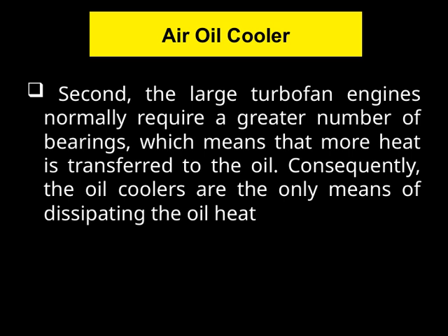This is where oil coolers come into play. They are essentially the only means we have to dissipate the heat from the oil. Without effective cooling, the oil could overheat, which could lead to lubrication issues or even engine damage. So, in essence, the air oil cooler is a vital component in the engine's thermal management system, especially in large turbofan engines. It ensures that the oil stays within safe temperature limits, helping to keep the engine running efficiently and safely throughout its operation.